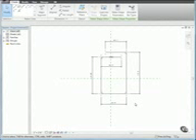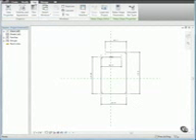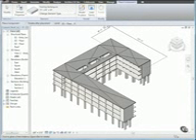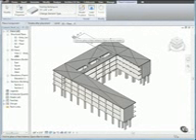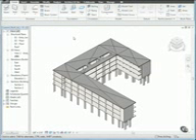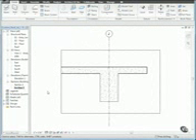Click the View tab, and on the Rebar Shape Editor panel, click Load into Project. The new overlapping rebar family is now loaded into the project. Press Escape twice, and let's launch the Rebar Shape browser. Open the View Section 2 and select the concrete beam.